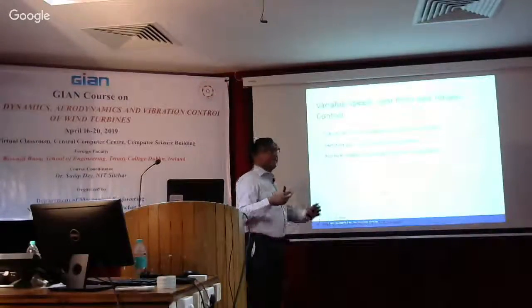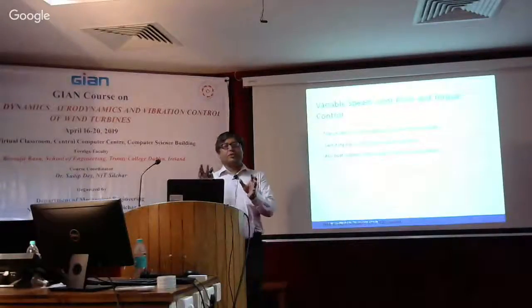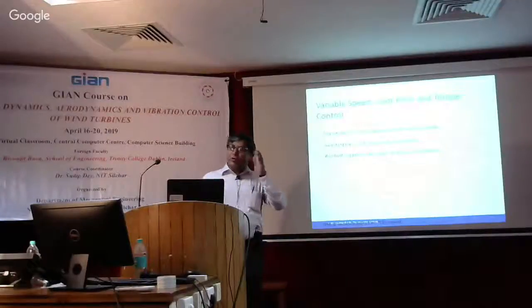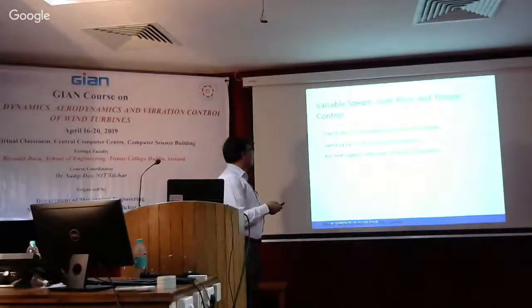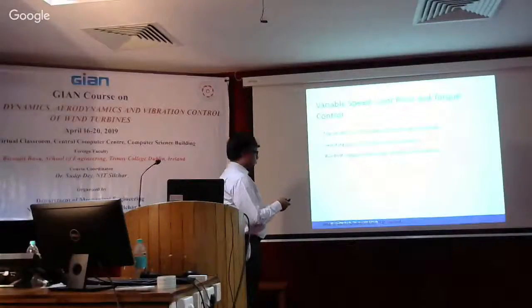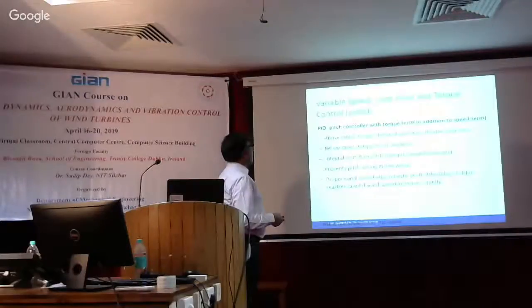So you do not change the torque and speed simultaneously. You have two things to play around with, and you don't change those simultaneously. You hold one constant and then change the other to get it optimal.